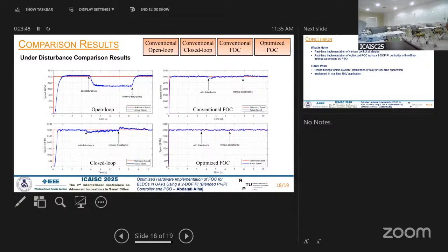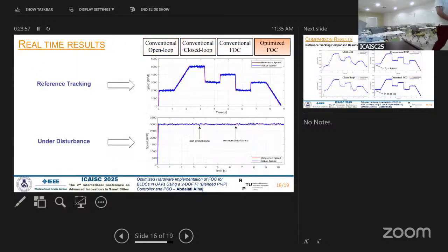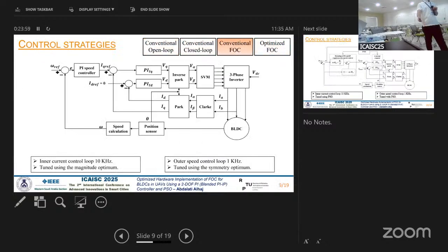Because the motor has a mass and inertia, and when you move something with a mass, it takes more time. How is the ideal case like this? That's a very good question actually, because that's why I told you that we must use very high-end microprocessors and advanced techniques. In the inner control loop, we operate the system at 10 kilohertz. To get high resolution, 10 kilohertz means 0.1 millisecond.